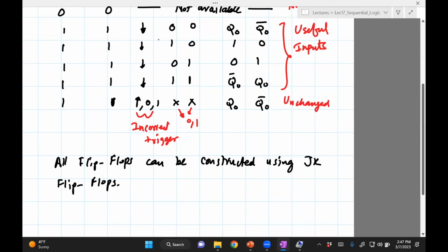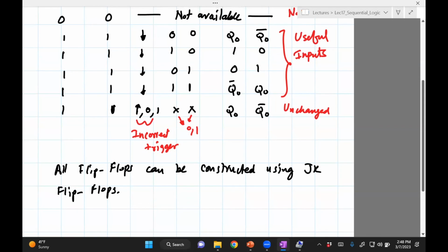The equivalent for gates is, I think, the NAND gate. If you use the NAND gate, you can construct any gate. Okay, one more thing and we'll stop. I'll show you how to use a JK flip-flop to construct a toggle flip-flop. A toggle flip-flop will just toggle the inputs. It'll make ones zeros, and zeros ones. So let's see that, and then we'll stop.